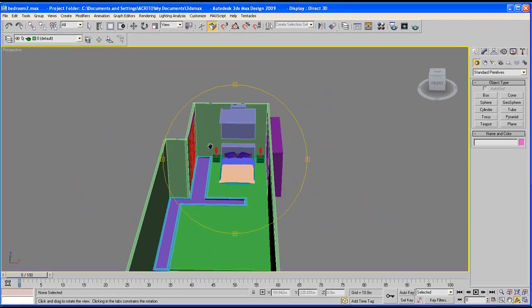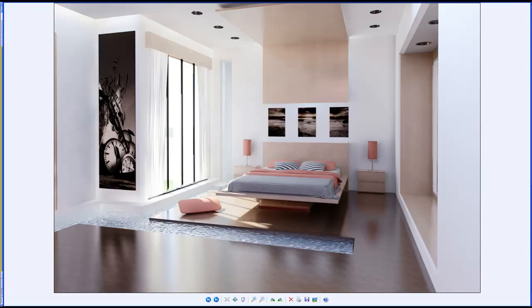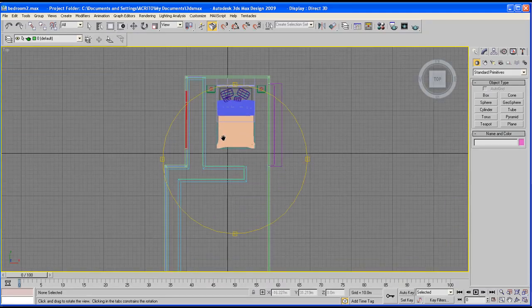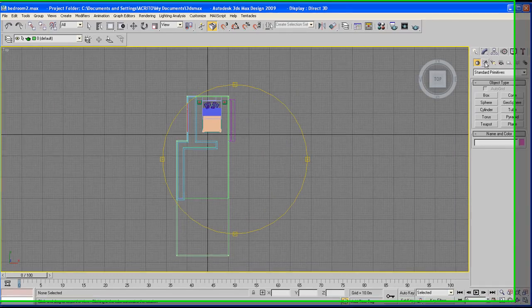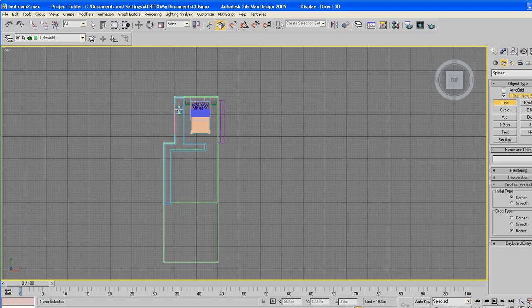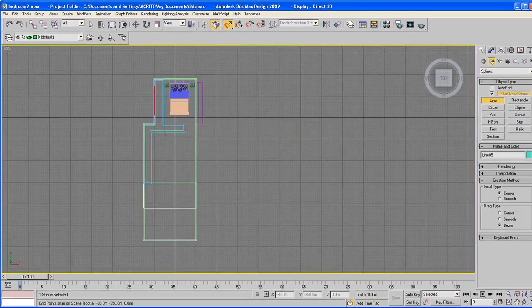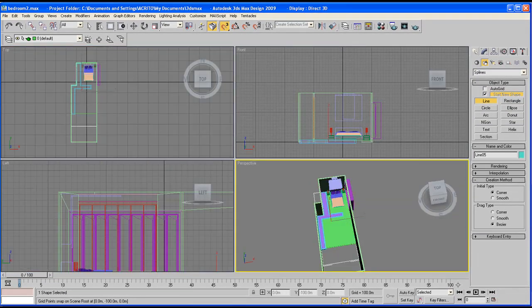Okay, now we're going to create the ceiling. Now we've got quite a lot of light in there. Go over to the top viewport. Select the shapes under create. Get the line, hit S to snap to grid. And just draw the ceiling. The reason I didn't take it down here, this will be resized later. If not, then we'll increase the size when it comes to rendering.